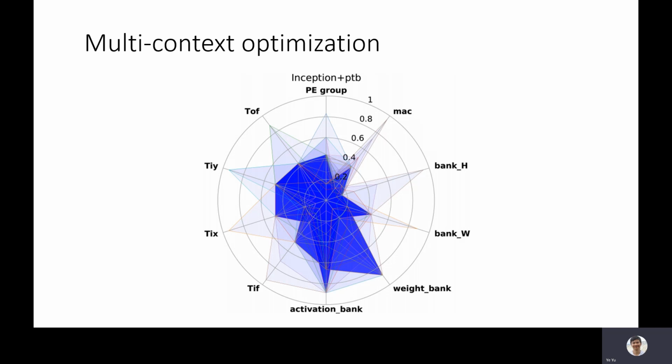the accelerator architecture. While maps are mainly devoted to convolutional layers of Inception v3, filtered weights can be transferred between the weight buffer and external memory for matrix-matrix multiplication layers for PTB at the same time, with no or very little performance loss, since the layers of both DNNs are interleaved. This shows that optimal design for multi-context applications may not be a simple combination of designs optimized for the individual applications, and new optimization opportunity can be explored using our application-driven architectural design space exploration framework.